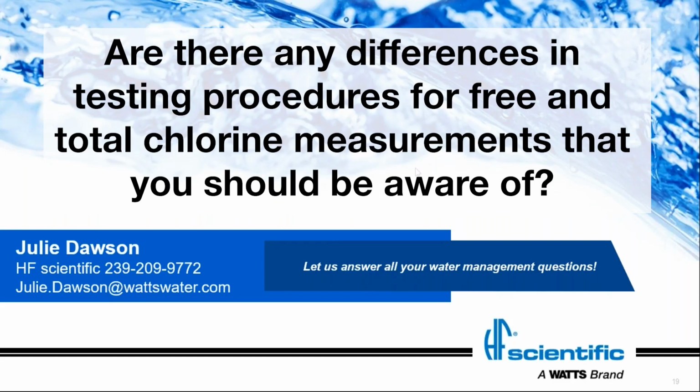For amperometric titration, that was actually one of the concerns I have about amperometric titration, is we need very good laboratory technique because we're going to be pouring the sample and we're also going to be stirring the sample. So we want to make sure that we're not stirring the sample too hard or too fast or creating additional turbulence that's going to strip that out of the water. So when you're measuring free or total there, we're just trying not to lose chlorine. But that's particularly important for free chlorine. That's what you're going to strip out of the sample.